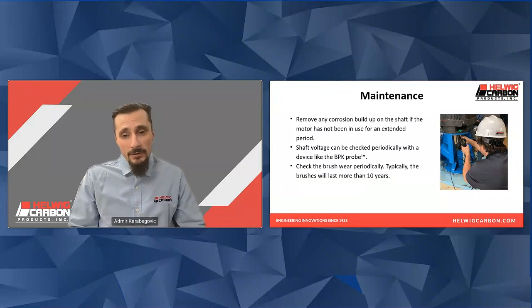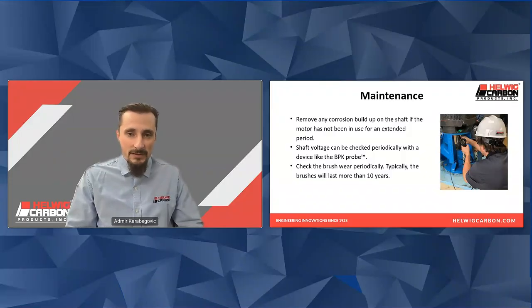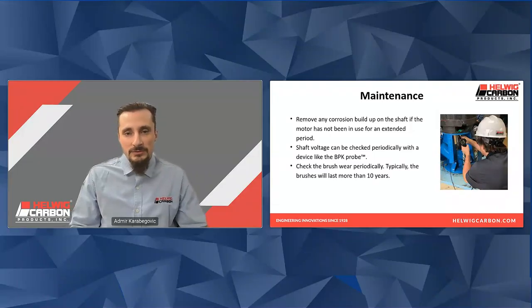If there are other applications where that oxide is on there continuously, in those applications we can go with a different grade that has a little bit more cleaning action, and/or we increase the spring force of our kit to reduce the contact resistance. So there's a couple things we can do in tough applications.